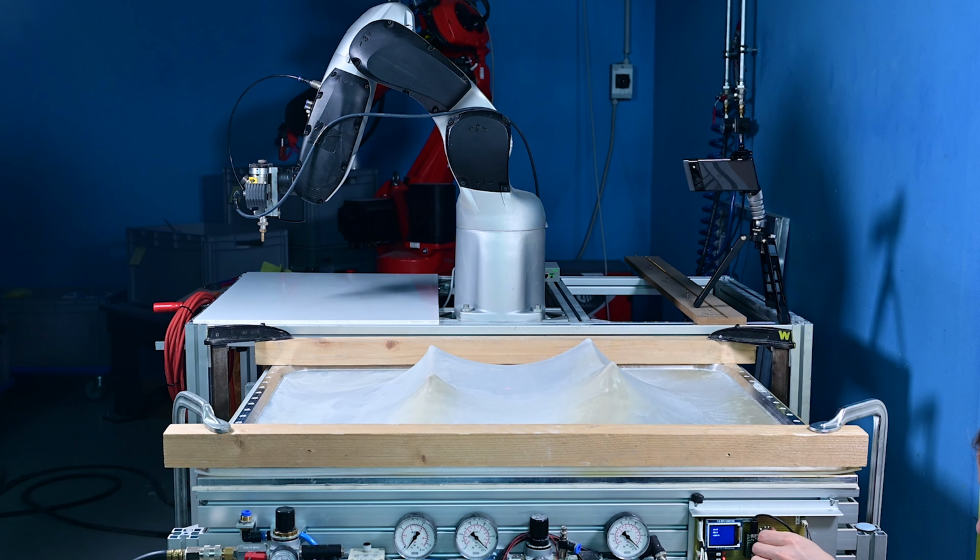to use. An elegant way to fabricate a panel is the use of robotic 3D printing. Here we print the test panel using plaster. We believe 3D printing of concrete directly into the mold would be a very exciting way to produce highly customizable concrete panels with a perfectly smooth outer surface. Another option would be to use a lamination process to produce fiber-reinforced panels. Our gypsum panel is cured after a few minutes and can be demolded. The machine is now ready for the next panel.